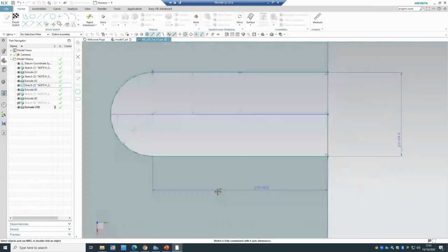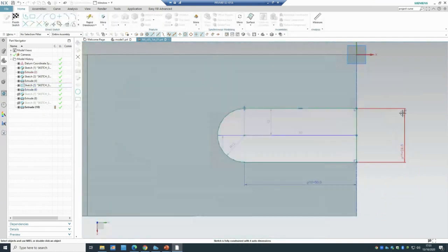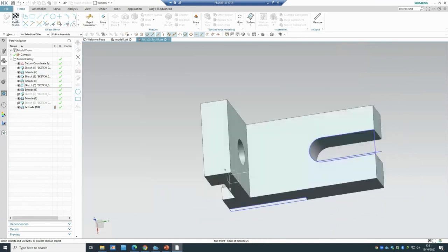It's the 50. Either you put this one as 24, or you can make the arc and put that one as an R12, or radius 12. You can either put the 2-dimension for this one or make this one a tangent. So both of them are fine. You can either dimension or you can run it by the constraints. So these are different methods of doing it.